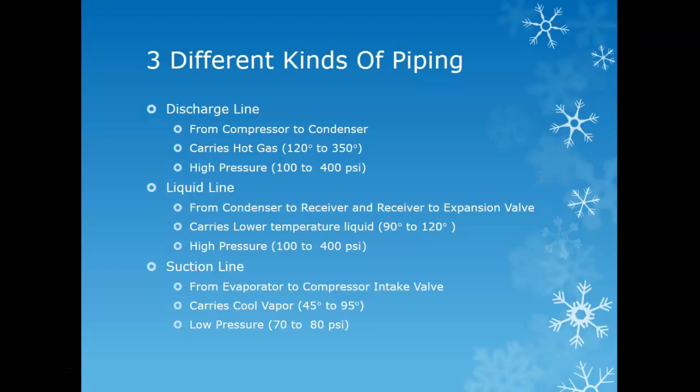Pressurize the tank, and that way the air's expanding inside the tank. When you spray this soapy water on it, it makes bubbles because the air's obviously coming out of it. Yeah, you're putting air in it.